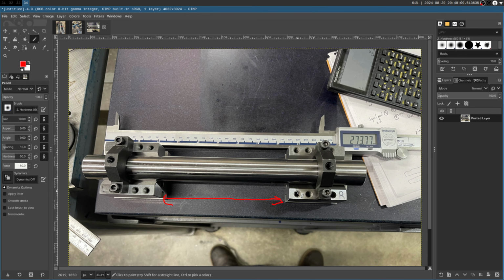They're also extremely square and parallel. These are, I think, within 1/10,000th of an inch, so about 2 or 3 micron, square and parallel. I could be wrong. Nevertheless, it doesn't actually matter what specification they're built to. That's really just what the manufacturer is willing to reliably produce these at. I specifically have gone through my V-blocks and my precision round stock, and I have looked for the roundest, straightest, flattest, squarest, parallelest stuff I have.